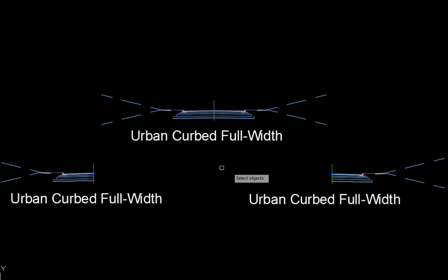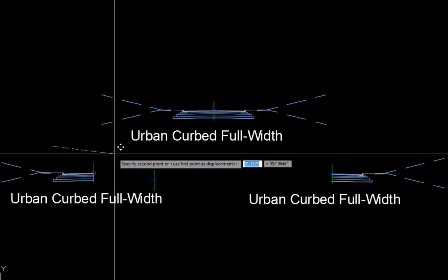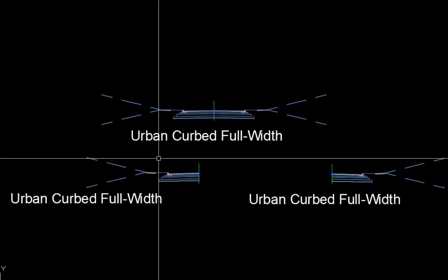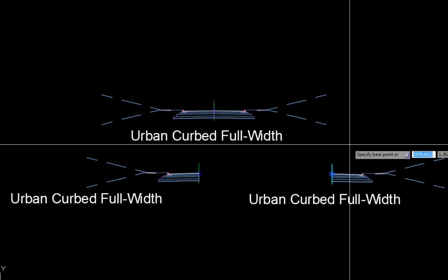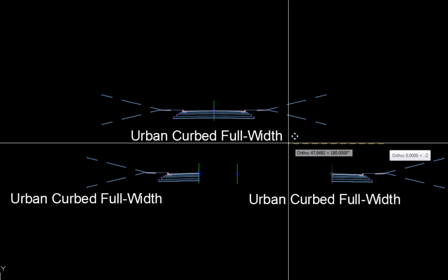To start move command, pick the left assembly marker. Move towards the center. Ortho on. Pick. Restart move command. Pick the right assembly marker and move to the left.